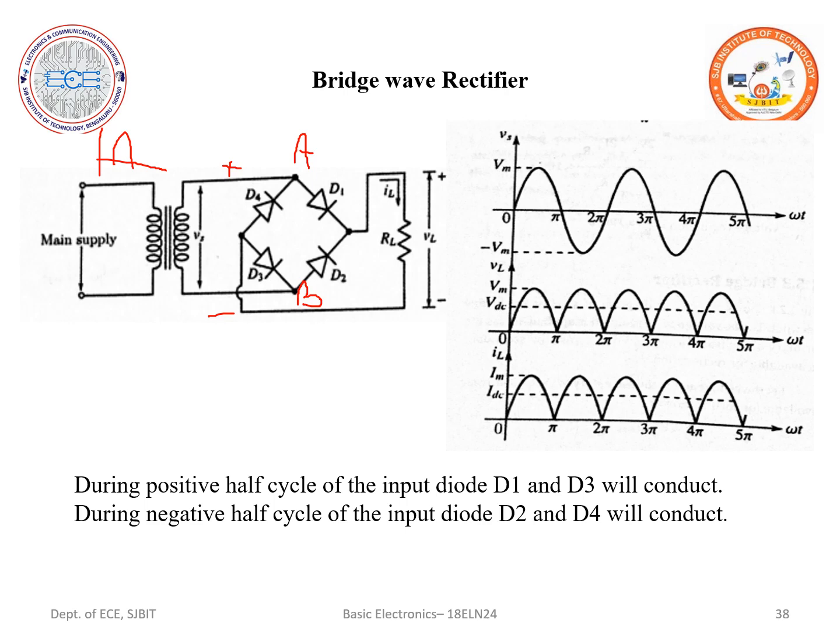Look into the diode D2. Is it in the forward bias? No, this is because it is a reverse bias. Now look into D3. My cathode is connected to the negative terminal, so I can say my D3 is forward biased. So my diodes D1 and D3 are forward biased, whereas my diodes D2 and D4 are reverse biased.